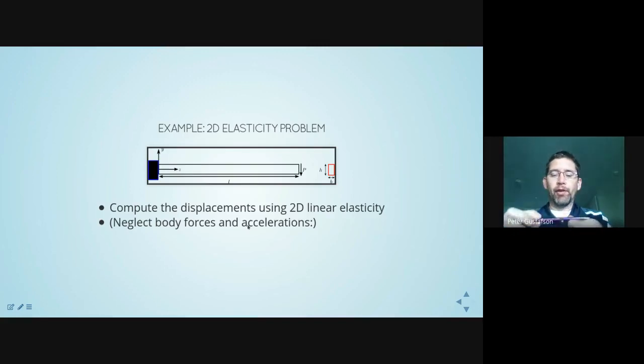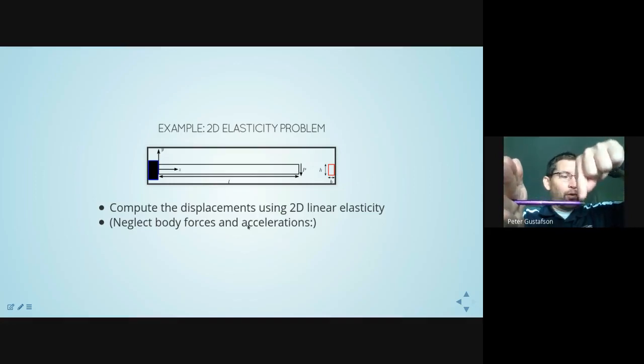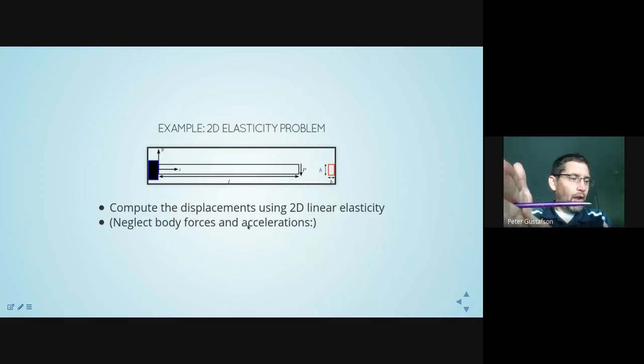A cantilever beam is a beam that extends from a typically assumed rigid structure. So I am going to say that this beam is kind of like a diving board with a person who is standing on the end, perhaps bouncing, ready to jump, but the other end of the board is fixed into the wall, and that fixation is assumed to be rigid. So this is the type of problem that we're going to start with, and we're going to do a fully 3-dimensional elasticity calculation. Really 2-dimensional, I should say, 2-dimensional elasticity assumption.